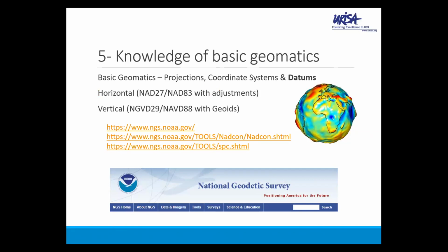So one has to convert ellipsoidal heights to geoidal heights using a conversion to get to elevations that you would measure on the Earth relative to sea level. Right now, we do that through the use of geoidal conversions, and the geoid that we're using right now is Geoid 12B. All of this information can be found with more clarification than I can possibly provide at the NOAA site, and those are the sites that I reference here.